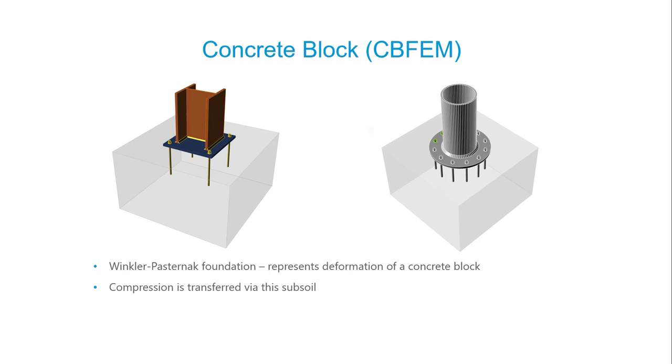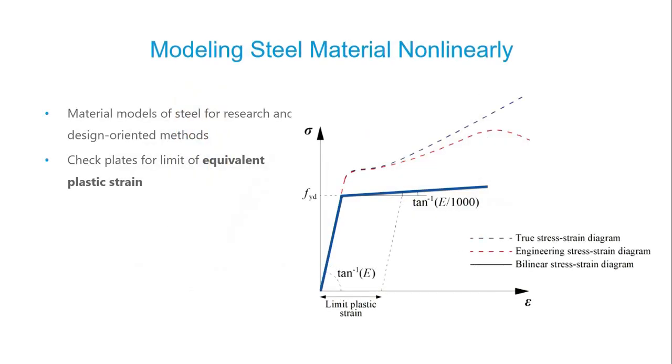Tension is carried by anchors, by anchor bolts, and shear is carried by the shear resistance of the anchor bolt, by bending of the anchor, or by friction. The analysis is made as material nonlinear, by default, and delivers stress-strain results for code checks.